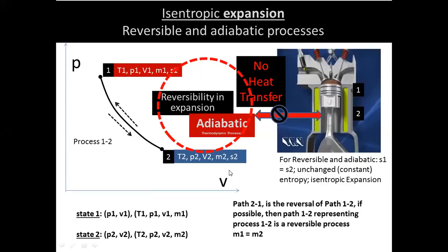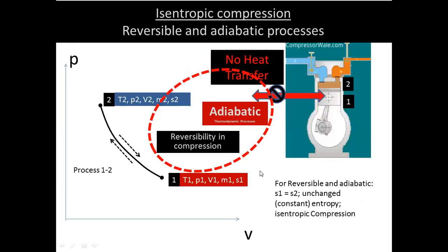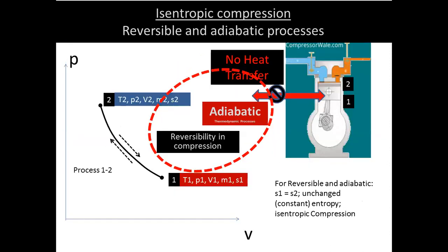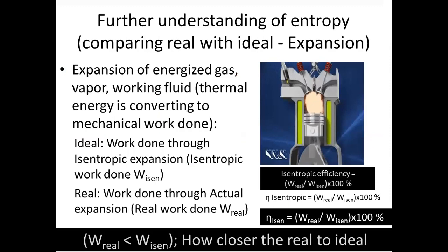And combining all this, reversible adiabatic is to achieve the isentropic nature. 100% isentropic efficiency is the ideal case, but we can have at least over 90% of the efficiencies in compressors and all. Okay, good. So nice. Try to understand this. I'm sending you this note.